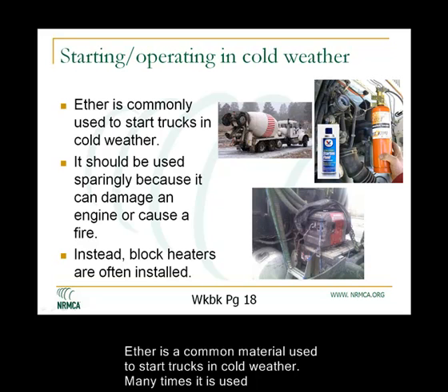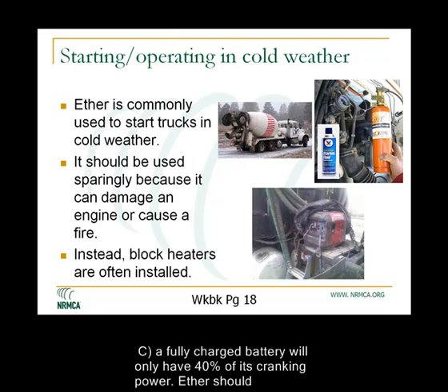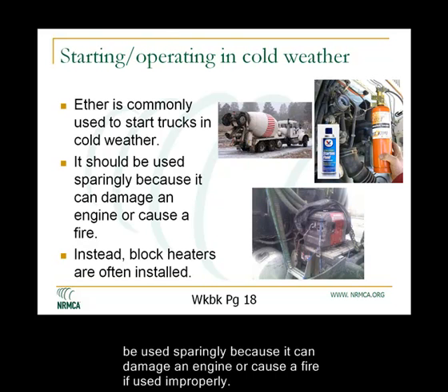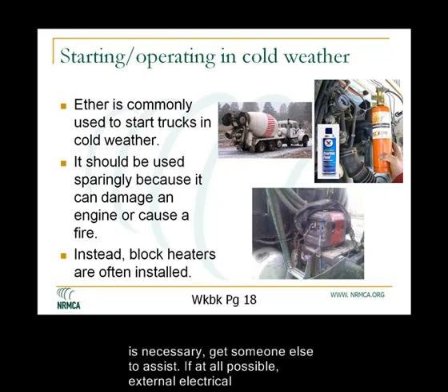Ether is a common material used to start trucks in cold weather. Many times it is used to reduce wear on the battery when trying to crank a cold engine, because at 0 degrees Fahrenheit or minus 18 degrees Celsius, a fully charged battery will only have 40% of its cranking power. Ether should be used sparingly because it can damage an engine or cause a fire if used improperly. The CDP should try to crank the engine 6 to 8 times before using ether. If ether is necessary, get someone else to assist.